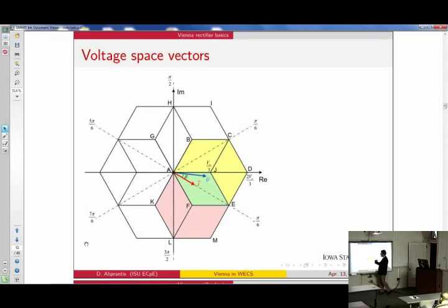Whatever voltages you want to get on an average basis, you determine which ones to turn on and how long to keep them on, and you can get that voltage on average. And then, of course, because this is an AC voltage, the voltage basically rotates around like this all the time. So you use different switchings as the voltage moves around. It turns out for this type of topology that depending on where the current is, the red one, you can only use a subset of these points.